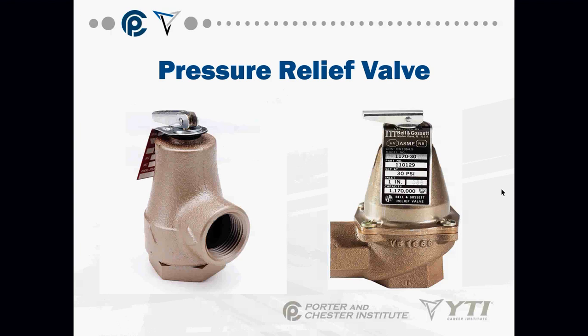Your water reducing valve, like the one we're talking about, will probably be installed before the water feed valve. So you're taking pressure from water that's coming into the building, reducing it down to a usable pressure to feed the water feed valve. So they will most likely be piped in series with each other. Okay.